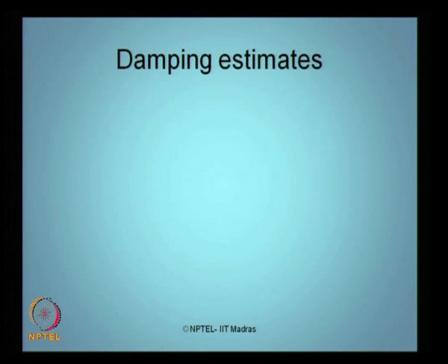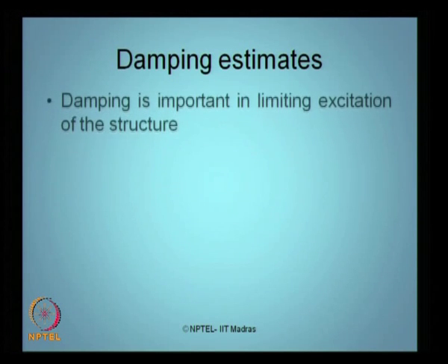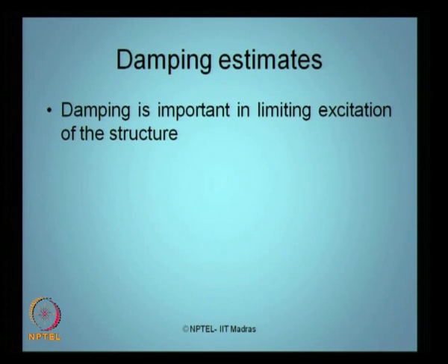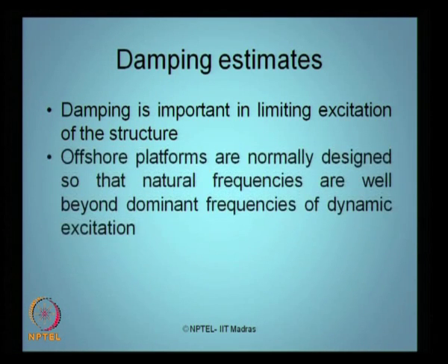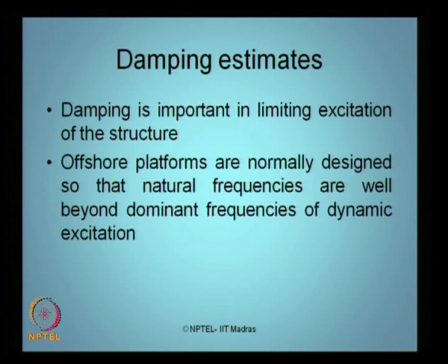Interestingly, as we also saw, damping plays a very important role as far as hydrodynamic loading on offshore structures is concerned. So let us talk about the damping estimates very quickly now. Damping is very important when you excite a structure at a limiting frequency. Offshore platforms are generally designed not to have the natural frequency well within the domain of the excitation frequency. That is a general design concept in offshore structures.